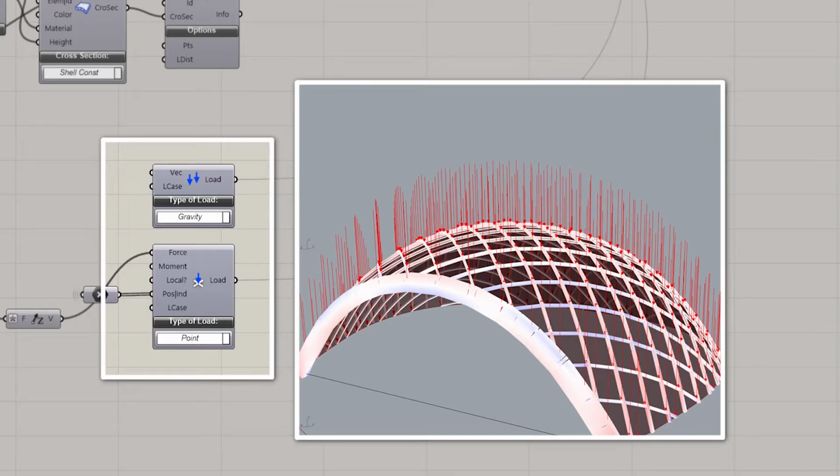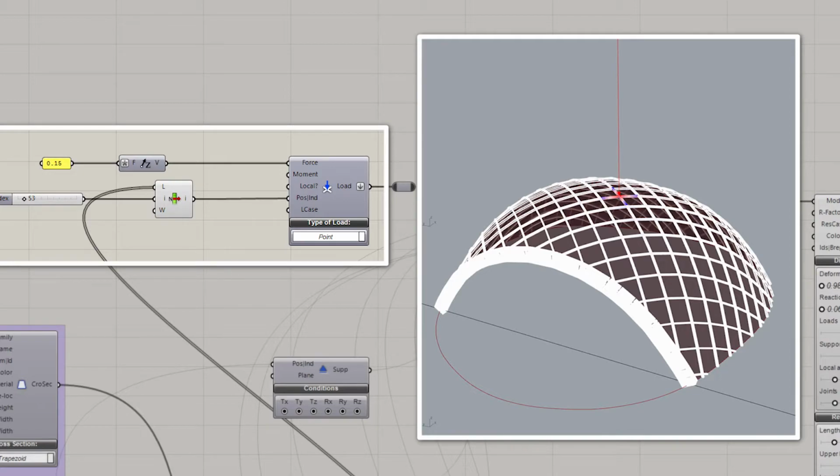The next step is assigning the loads. A combination of the loads is assigned with specific magnitudes at specific points. The loads are also multiplied by a safety factor. In this case, I assigned 1.2 times the weight of the structure, as well as 50 pounds per square foot on the outside surface. I also assigned a load of 150 pounds applied to individual joints one at a time to represent someone climbing on the structure during construction.